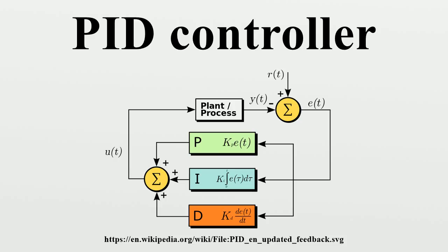Manual tuning. If the system must remain online, one tuning method is to first set the I and D values to 0. Increase the P until the output of the loop oscillates. Then P should be set to approximately half of that value for a quarter amplitude decay type response. Then increase I until any offset is corrected in sufficient time for the process. However, too much I will cause instability. Finally, increase D, if required, until the loop is acceptably quick to reach its reference after a load disturbance. However, too much D will cause excessive response and overshoot.